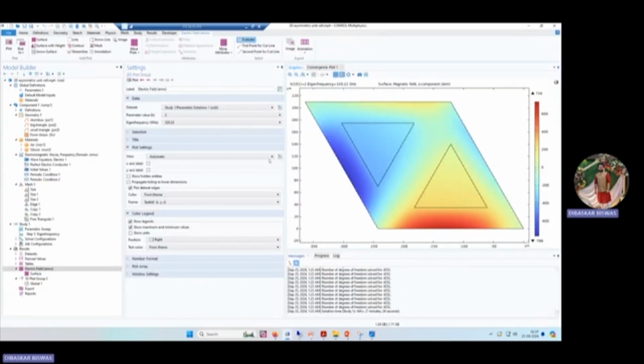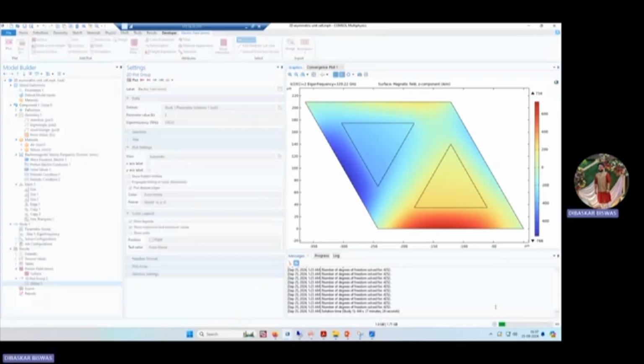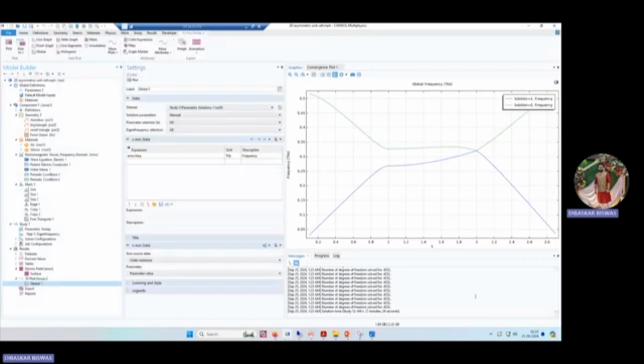Okay, so for the symmetric case, we'll be checking the band diagram here. We covered the band diagram analysis, and also the topological edge state in this first part. In the next part, we'll see how, based on these simulations, we'll be designing the entire waveguide structure. The interface will behave as the waveguide, and we'll see how the terahertz signal passes.